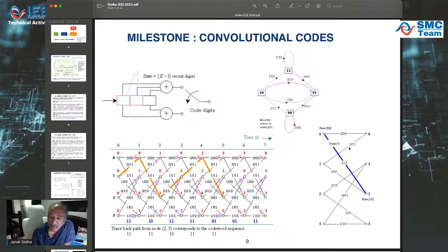He basically concatenated this several times, and he placed the received sequence underneath. He used a very simple way to eliminate branches and ultimately choose the branch with the lowest metric and trace that back in order to output the corresponding sequence. We don't have time to get into this algorithm, but the encoding process is certainly easy, and the Viterbi algorithm is what you see it is.